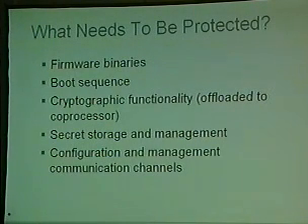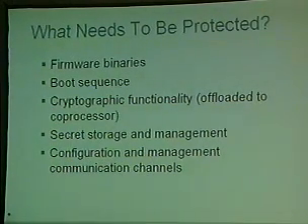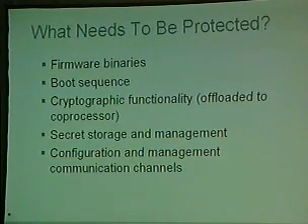What needs to be protected? Well, basically everything we just talked about that can be attacked. Most specifically are the firmware binaries. Many times it's a very low-cost attack where you can just go out and view the stuff that's sitting out on open websites, usually support websites. Next is the boot sequence. You definitely don't want to have the ability for application code to step back and reprogram firmware.